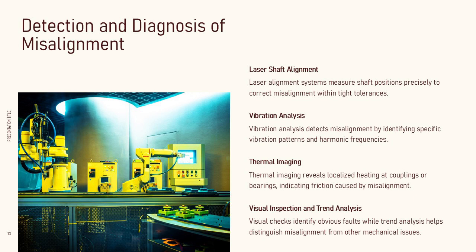Trend analysis and historical data play a crucial role in distinguishing misalignment from other faults such as imbalance or bearing defects. A systematic diagnostic approach ensures that misalignment is correctly identified and addressed, preventing unnecessary repairs and improving maintenance effectiveness.